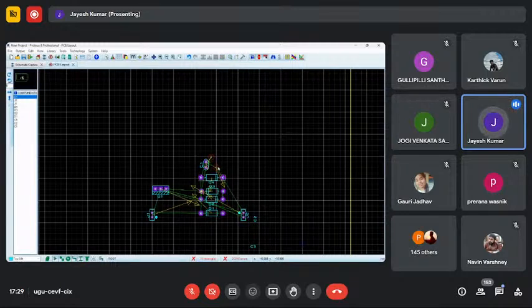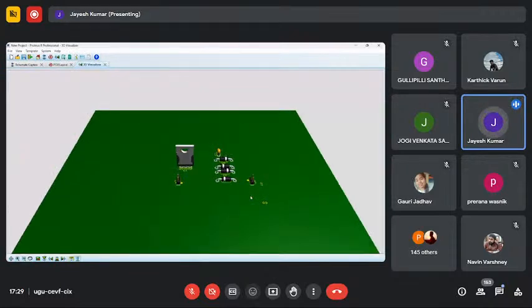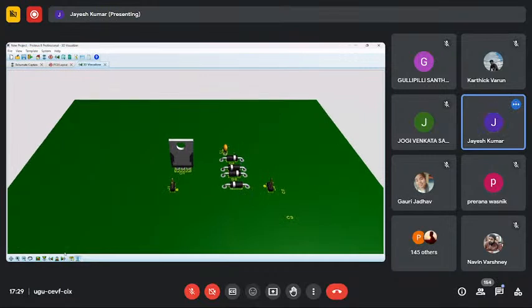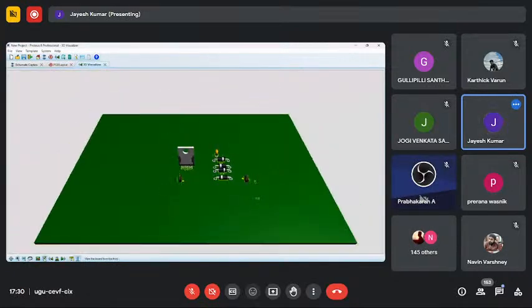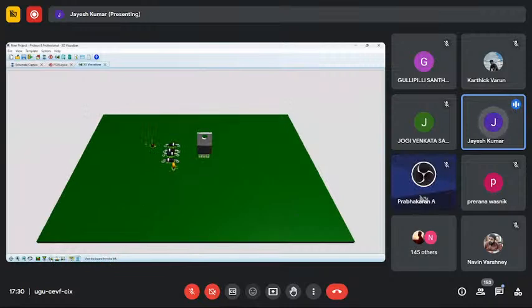So I've arranged all the components here, and now I just have to go to visualization mode and see my PCB in which I connected all the 4 diodes and 2 capacitors, and flip all this. After that, you can solder it or directly use the schematic PCB. You can change or check from all the angles.